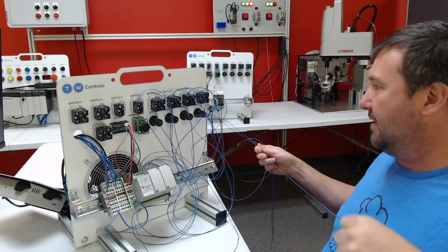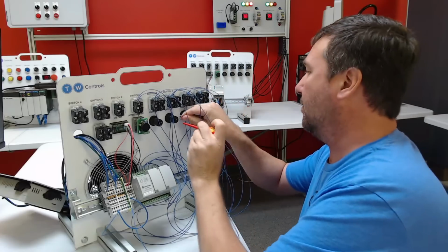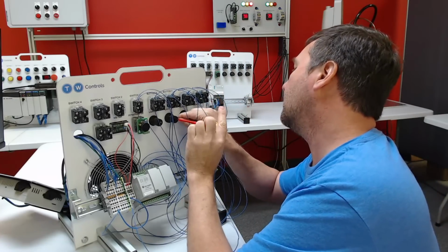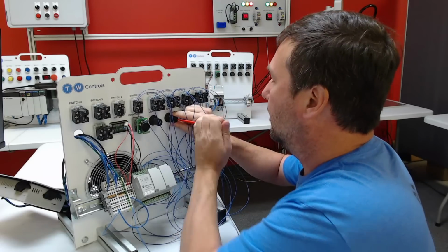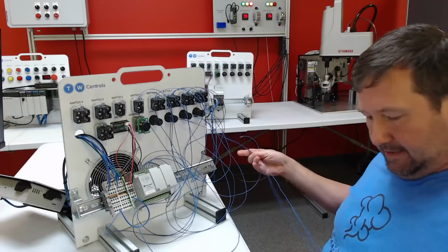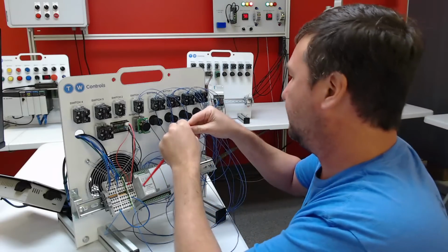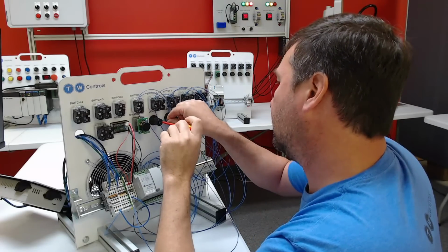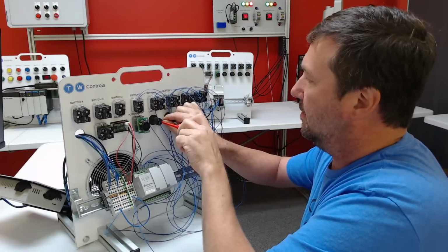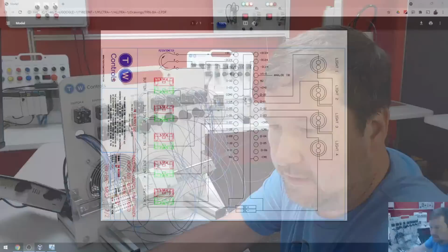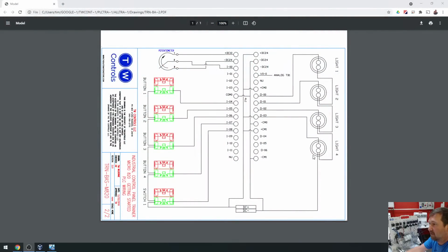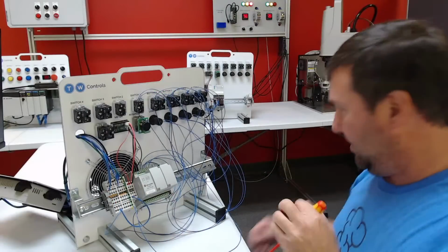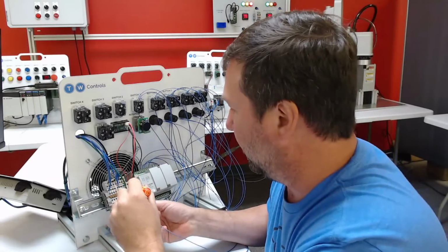And then I'm going to take it and an additional wire to light 3. And I'll take it and an additional wire to light 4. And then if we look here, all of these are jumpered together, and then that wire is going to go to our minus DC. So I'm just going to connect it to the right set of terminals.